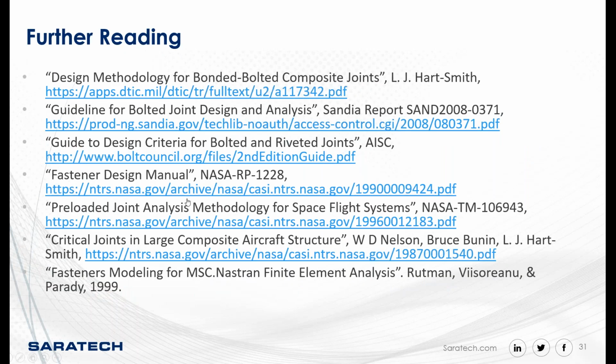And then we have one more question for you, Derek. We tend to ignore the moment contributions recovered when post-processing fastener loads, tension, and 2 shears with a 6 DOF stiffness CBUSH. Is that conservative? Yes, I think it is.